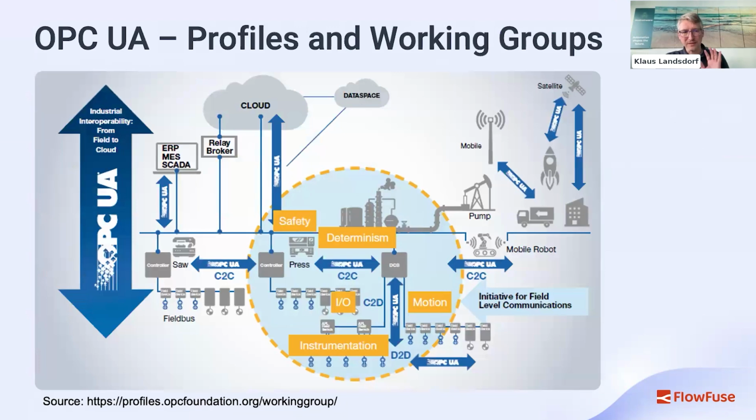Okay, and it could be very complicated, as OPC UA is really ready to use from sensor to satellites. That means we really have every area in the industry where you are able to use OPC UA. But you have to check whether it is the right tool for your use case, because other protocols like BACnet or MQTT or Modbus, like in the energy field, also work nicely, and have some security today.